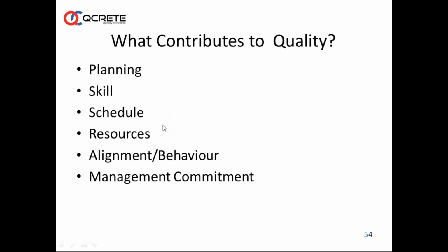Vishweshwariya Sulikeri is asking another question. What grade of concrete has to be used in industrial floor? See, industrial floors abroad they use M35 to M40 actually, and we need to consult the structural engineer. What loads are coming and what is the purpose. We generally have to consult the structural engineer, but abroad it is M35 to M40 actually.